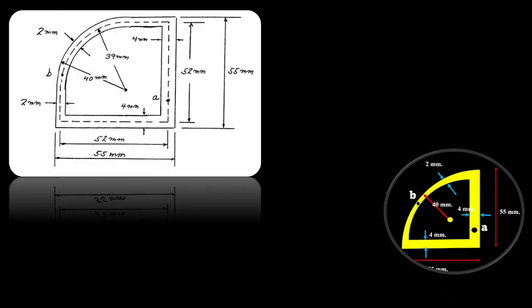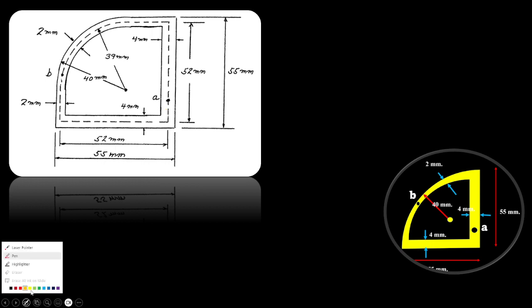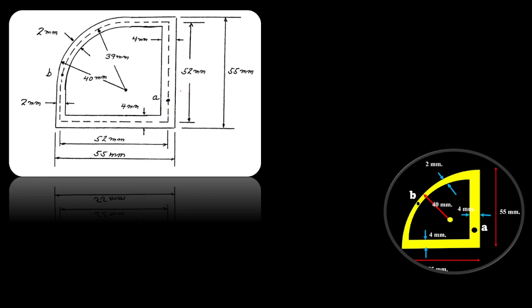To see how we can calculate this value, the very first step is to consider the center line, because we want to calculate A_m, which is the area enclosed by the center line. If you consider the dashed line for the center line and connect them together, it seems we have a big square, where the thickness here is 2 millimeters.